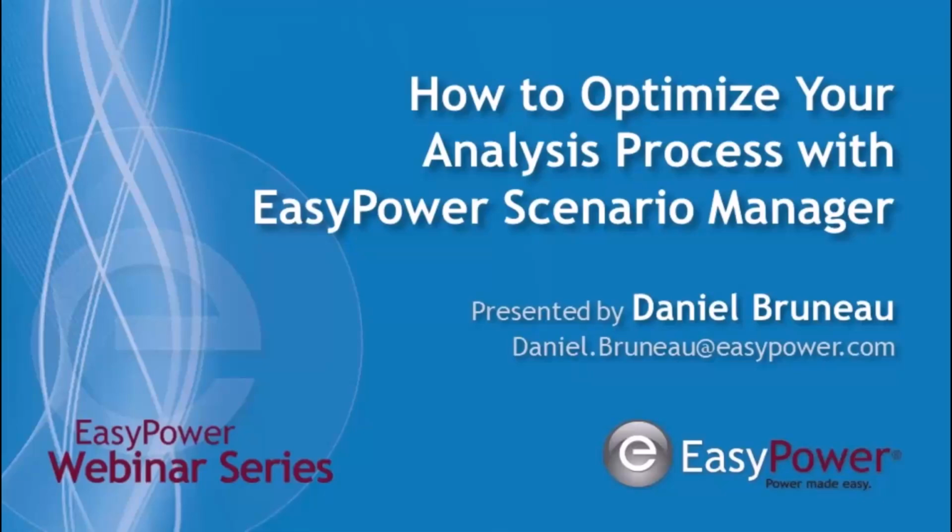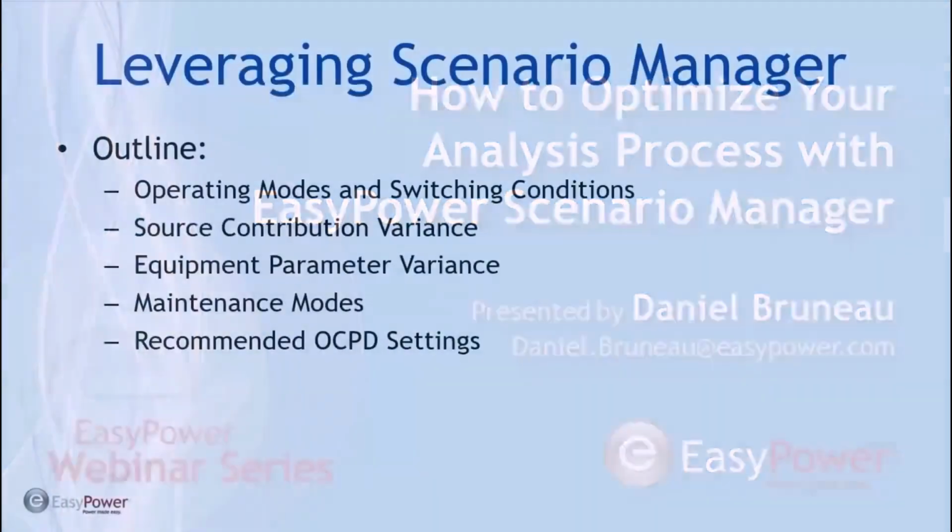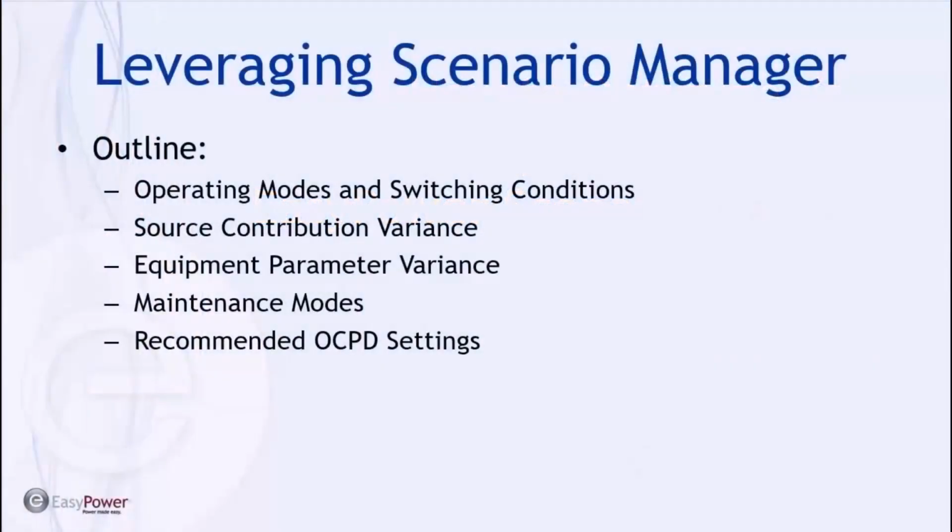Before I get into EasyPower and actually start the demo, I want to go over a quick outline of what we'll be looking at today, leveraging Scenario Manager. We'll be looking at, first of all, operating modes and switching conditions, source contribution variants, varying sources and scenarios, equipment parameter variants, looking at maintenance mode in scenarios, and then also recommended overcurrent protected device settings within scenarios.